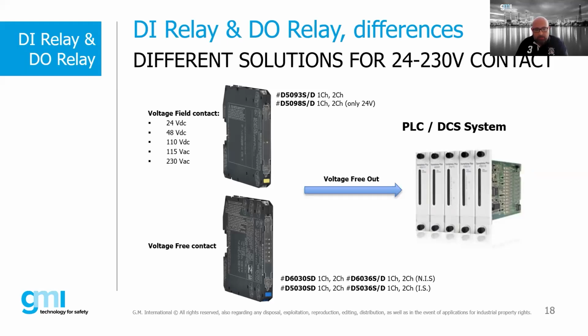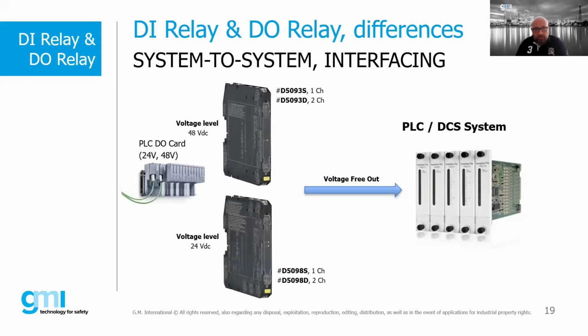The main problem in this case is that usually a relay is designed to switch important values of current, while a digital input card usually manages currents lower than 100 milliamps. In this situation, we can face problems of oxidation of the relay contact. Therefore, it is essential to choose a safety relay with gold-plated contacts, which allows us to switch currents lower than 10 milliamps.